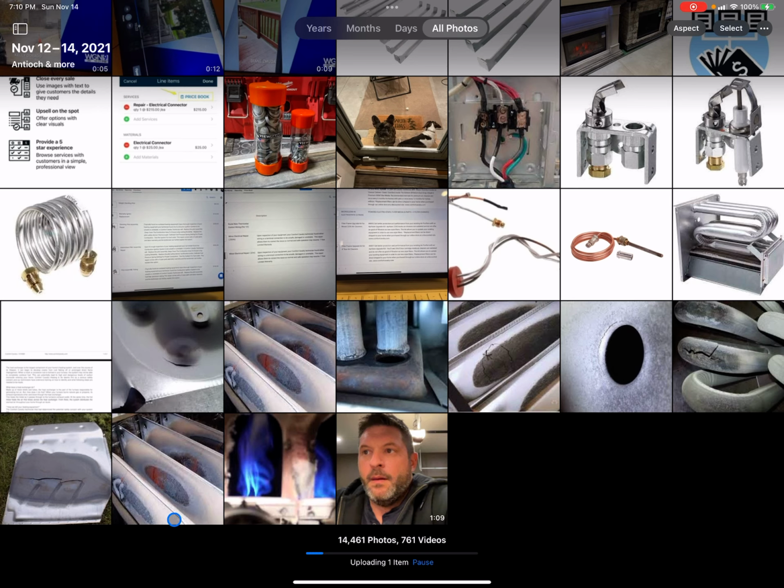Flame impingement is when the burners are not directed properly down the heat exchanger, and the flames are hitting the metal, whatever the case may be. We're not going to teach you how to find heat exchanger problems, but this is how I handle certain things I find: badly rusted, visible cracks, flame rollout, or wavering flames when the blower kicks on.